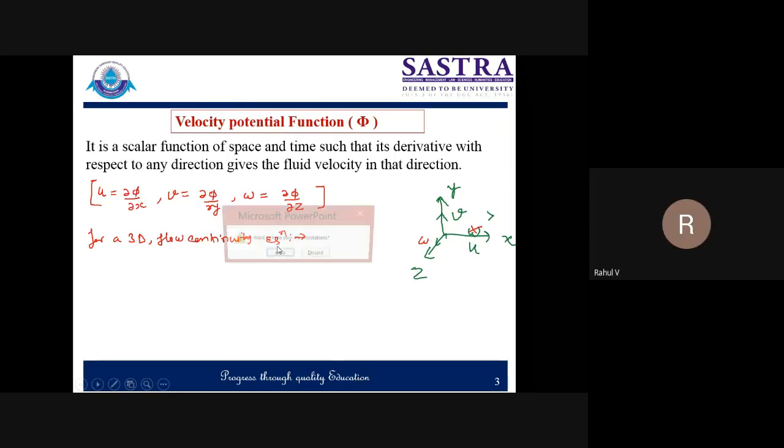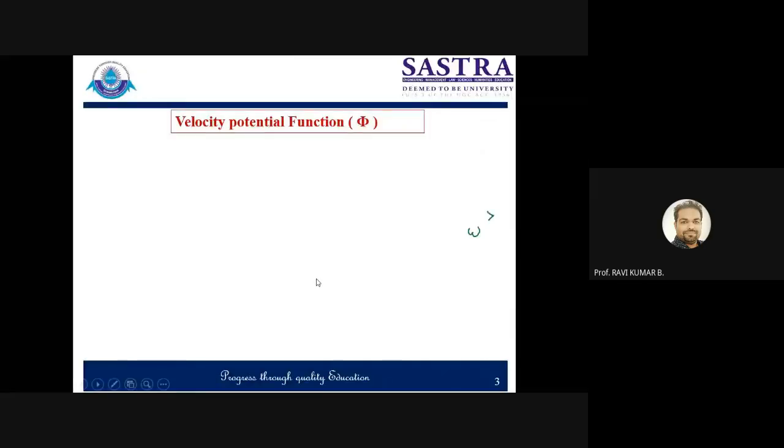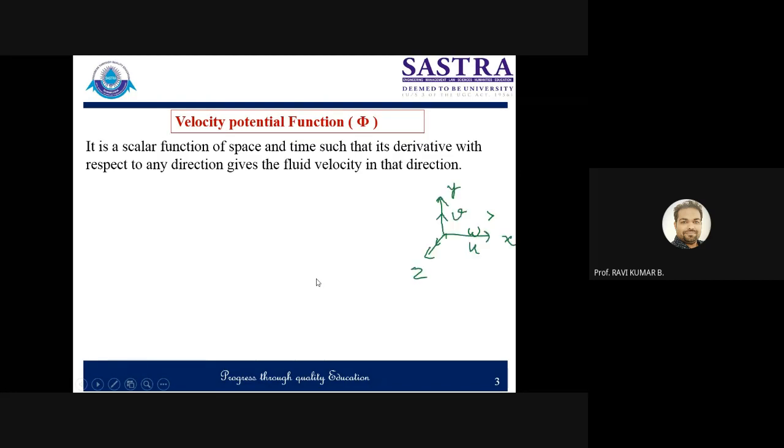Sir, dou u by dou x into dx, plus dou u by dou y into dy, plus dou u by dou z into dz equal to 0, sir. That means what? What is the case? Tell me the condition. The condition is steady flow, because otherwise the next term will also come, right?